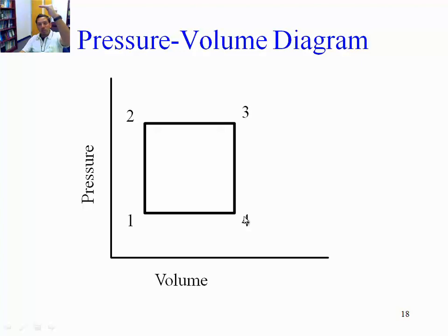That's when the piston is on the top, we remove the weight. By removing the weight, we're lowering the pressure, but it's occurring at constant volume. And then we expose the piston to a cold temperature reservoir, and by doing so, we reduce the volume back to the initial state at constant pressure. So the piston goes down at constant pressure inside the cylinder, and we regain the initial conditions. So this constitutes a power cycle, a very simple power cycle that is just academic.